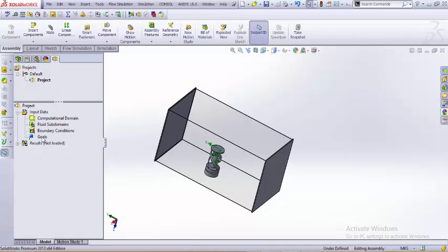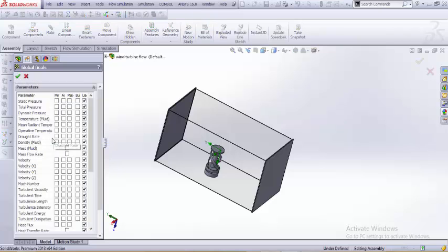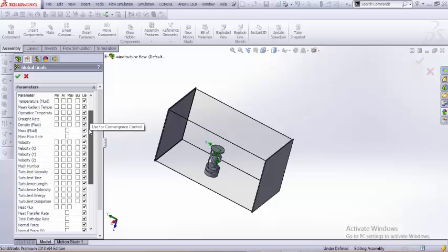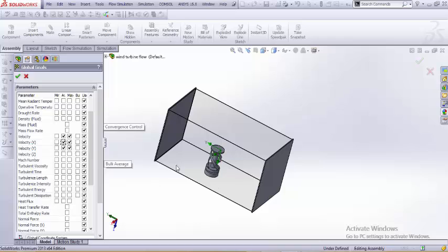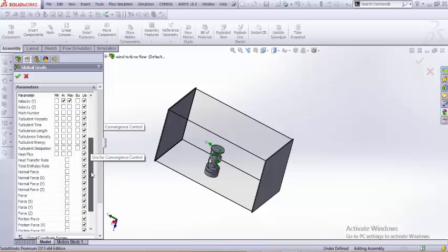Here we want specific goals, what we need. These are the global goals. Let's say we just need the static average pressure, total pressure, maximum total pressure, maximum dynamic pressure, and the average pressures. Usually we need the velocities, and we'll see why we need them. Since our reference axis and the flow axis would be Y, we'll just go for the Y-axis ones.